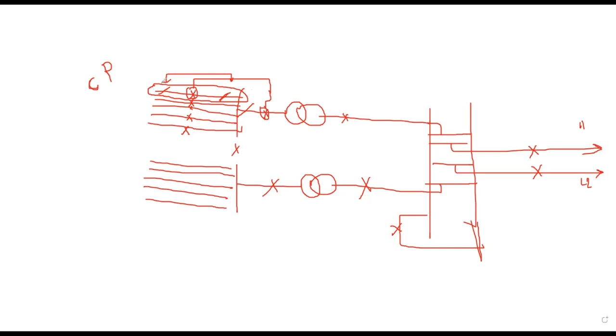These interlocks and the wiring of all these incomers, everything, we are looking at in the control and relay panel. So let's see: these are the two isolators, breaker, and CT, PT, all these signals, the status, or the controlling part and protection. All these should be accommodated in a panel. This panel we will call a control and relay panel. All the things which are accommodated in a panel, we will call a control and relay panel.